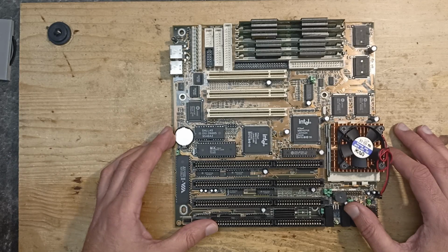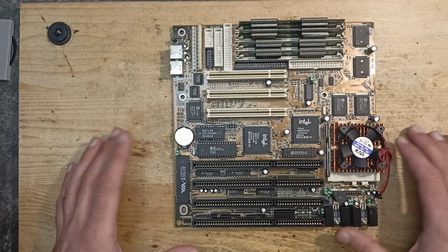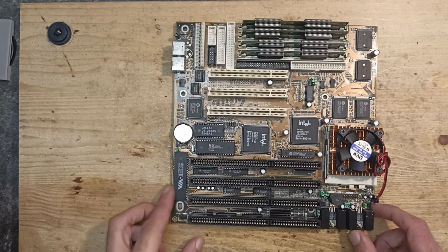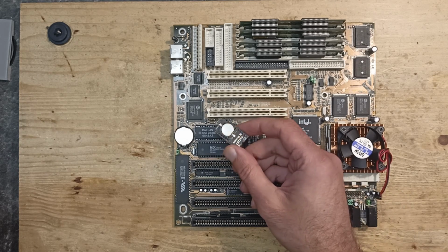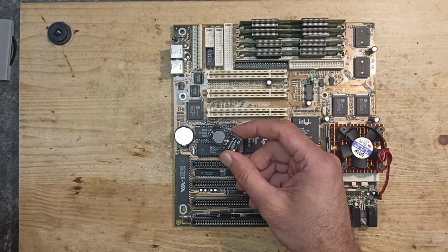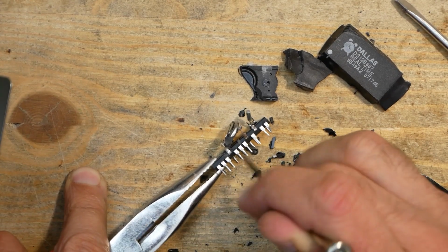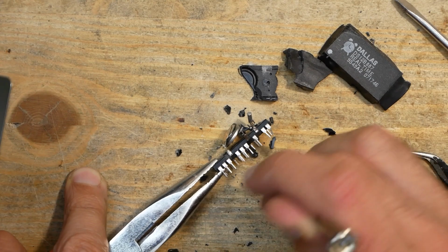So, what is the takeaway from this experiment? Of course, that we can add a battery on the mainboard if there is a place for it and use an RTC chip, that was quite obvious. The question was where to get those chips from. I was quite worried about the growing RTC chip shortage, as they are not produced anymore. The module, which I open sourced, is a good solution, but it is useful only as long as we can buy the required ICs. Luckily, there is an easy way to extract everything that is needed from those old black box RTC modules, which are still there anyway.